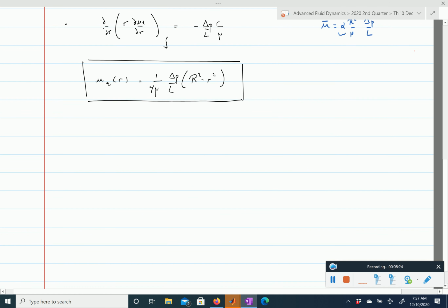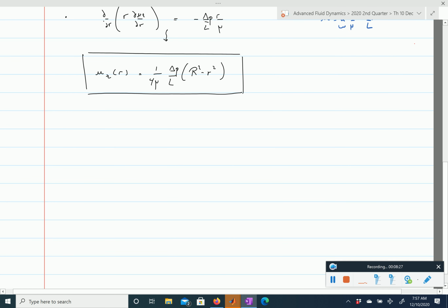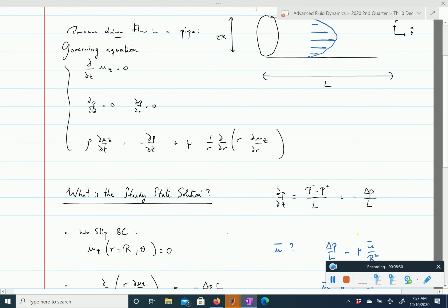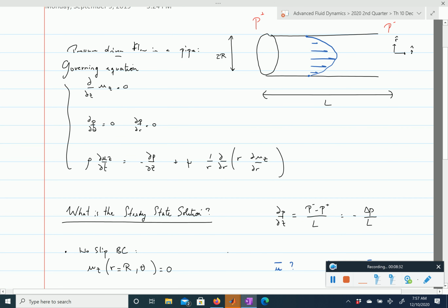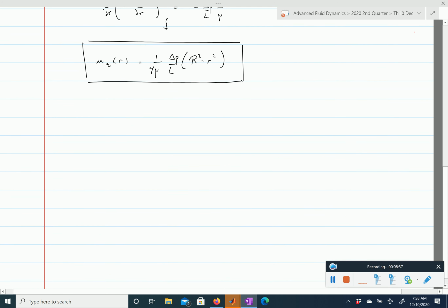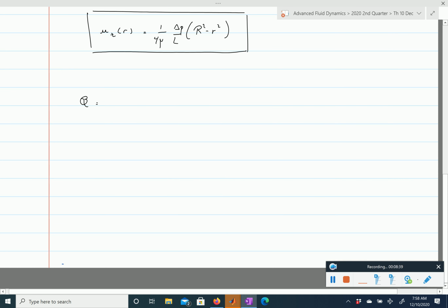So here we can then compute the volumetric flow rate through a cross-section. Right, so we think here about this cross-section here. What is the volumetric flow rate through this cross-section? We simply have to integrate the sum of the volumetric flow rates over elements of surface. The surface has a normal z, so it will be u dot z ds, ds being an element of surface on this cross-section, and we have to integrate over the entire cross-section.